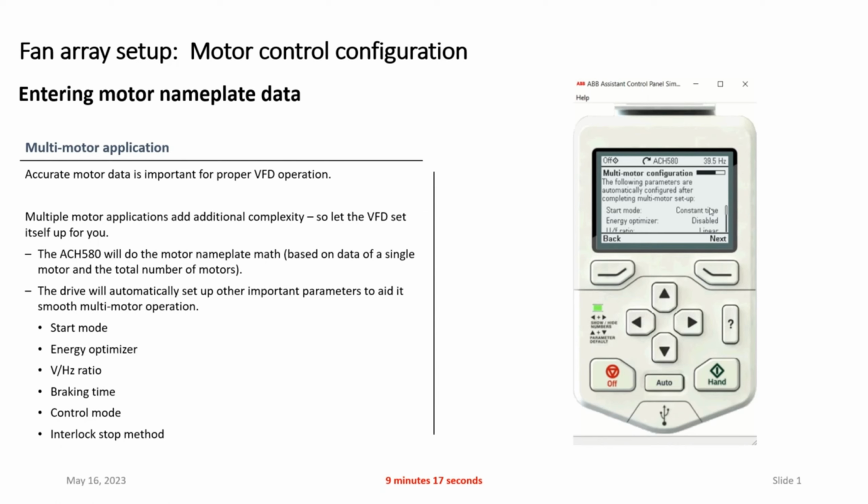That's another reason why on the start, the first thing you want to do is brake everything to a stop and then ramp them up, so the drive does not trip out on an overcurrent. So it's a much more reliable solution when you do these kinds of tricks in those kinds of application situations. So the start mode has been automatically changed for us.